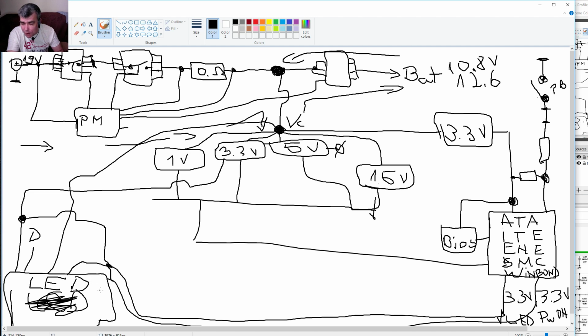You'll have test points saying power on, VLED, LED on, things like that. You can find these pins very easily. All the screens have test points on this pin.